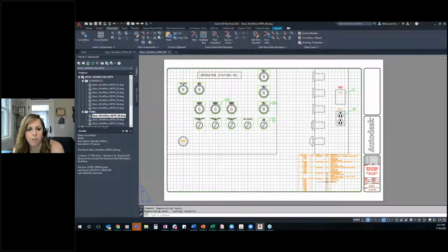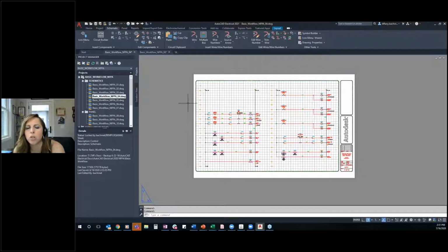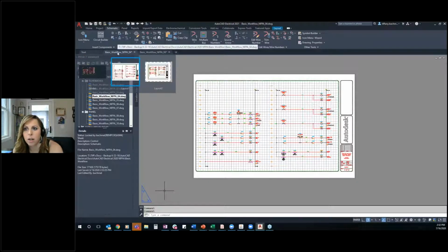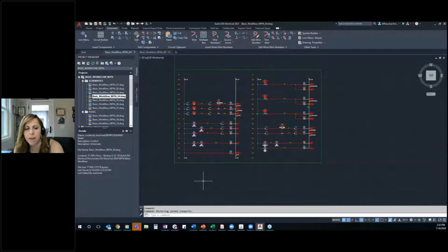And I know probably many of you are not loving the grid, and you can turn this off. It's just because I have grid on within model space. But it makes it so much easier for you to actually be able to work with your particular plot setups without having to manually do a lot of adjustments. So I'm a firm believer in setting up your templates with your title block and paper space, and a viewport into that. And once you do that once, you really don't have to spend a lot of time in paper space. You will spend 99% of your time here in model.